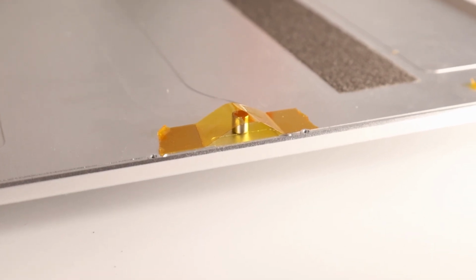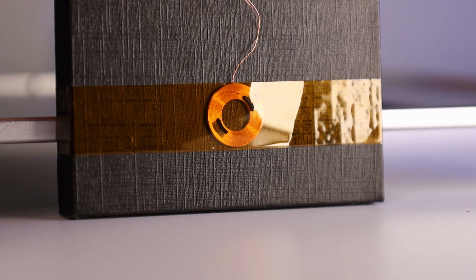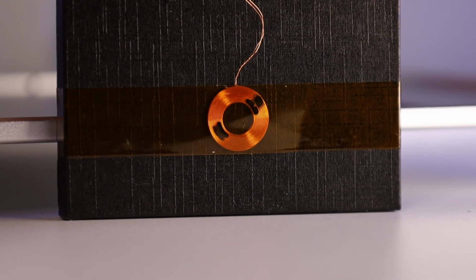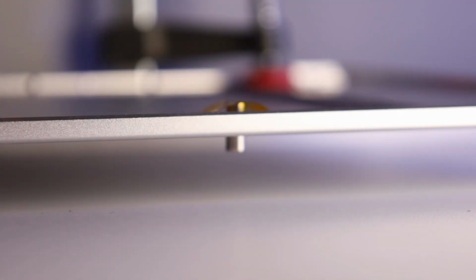We'd like to pick up the vibration pattern in different places on the laptop lid. For that, we need magnets and pancakes. Pancake coils to be exact. We place the pancake coil underneath the magnets and measure the voltage induced by the vibrating magnets with the oscilloscope.